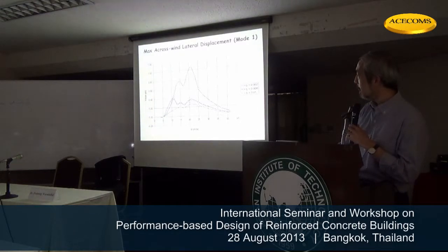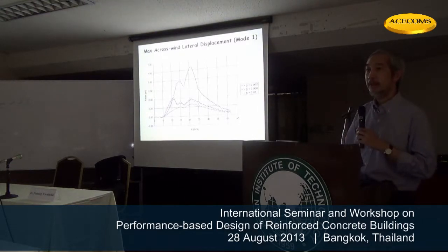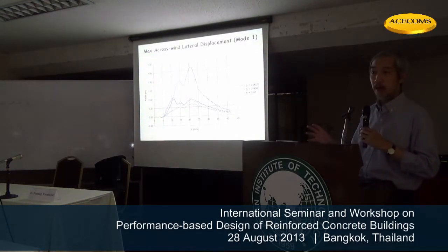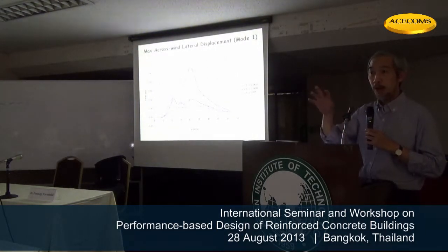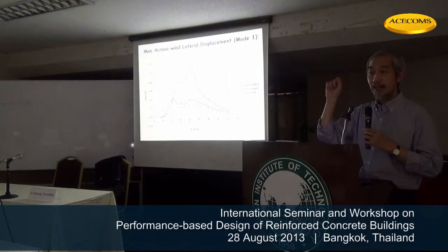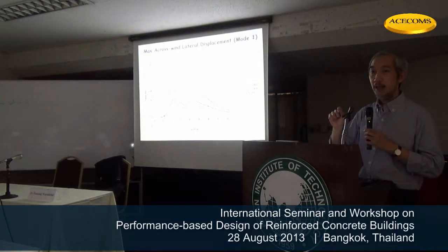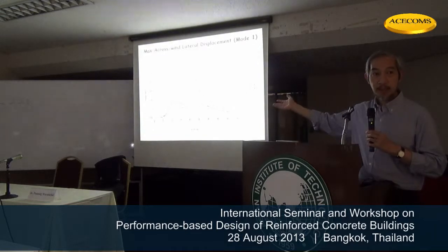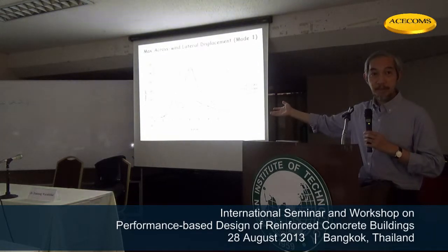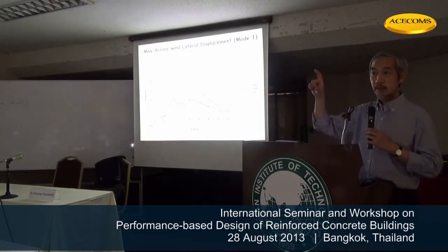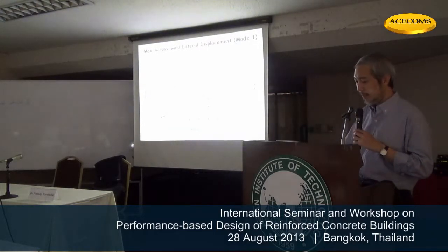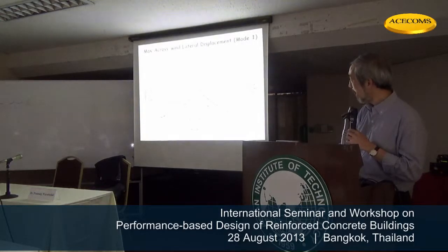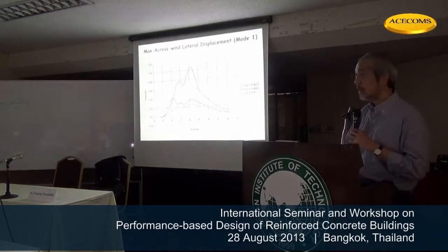We conducted analysis for 3 values of damping because we are not exactly sure what the damping value is. I hope you all understand what damping is. What is the damping value the structure has? Because it was the time before the structure was built, we have to guess. This is from statistics. It ranges between a low number and a high number. Low is very low, high is not so high, about 1%.